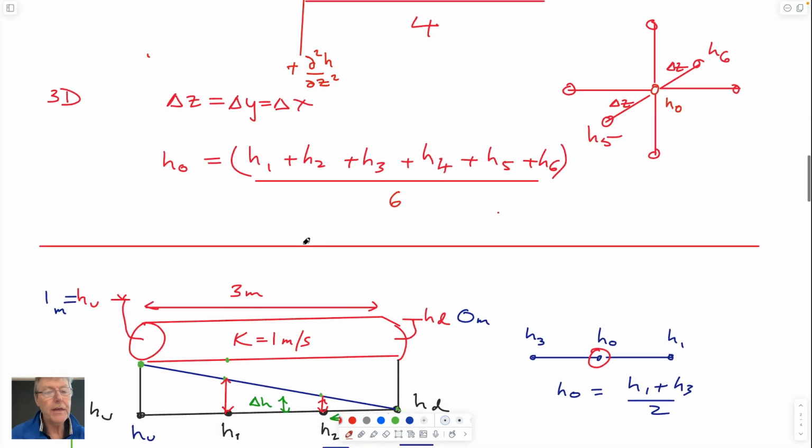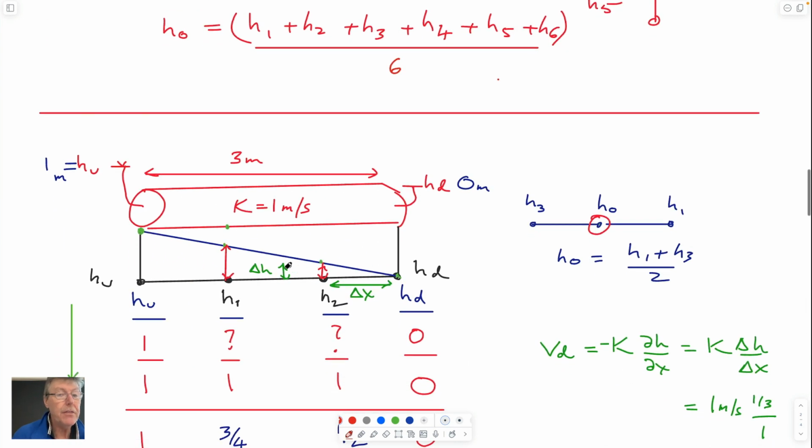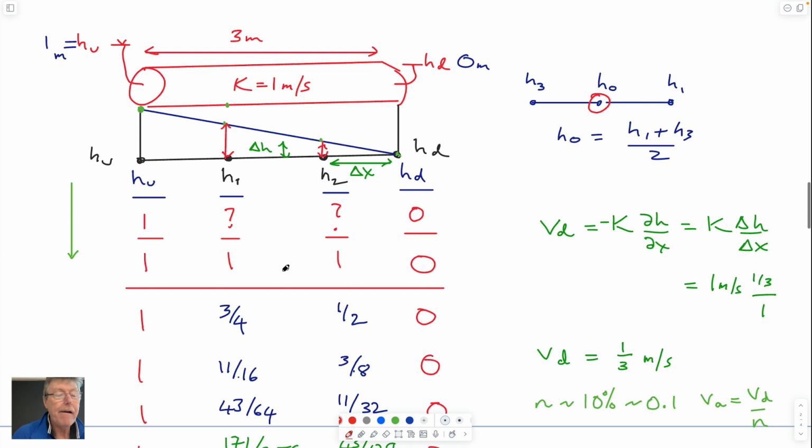So since we know that that is the rule, we can define a method to do this pretty straightforwardly. The straightforward method is to take this core that we had before, which is kind of our aquifer. Instead of having just an upstream and a downstream node and one middle one, why don't we put 2 mid nodes in between the upstream and downstream? And then we can go about applying this template by putting it over the upstream node, the next one, and the next one first, doing something, and then moving it downstream so it covers 1, 2, and downstream next, right?